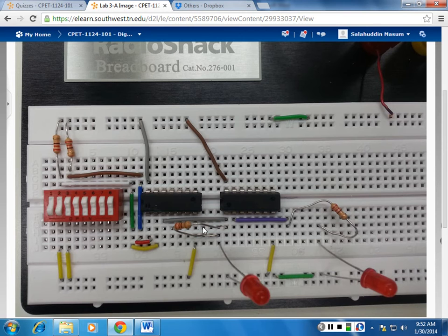And through the resistor, this is connected to pin 1. Do you see it? So basically, you are trying to see the output at pin 1, right? Because you are connecting the LED to pin 1. And remember, the other side must go to the ground, in most cases.